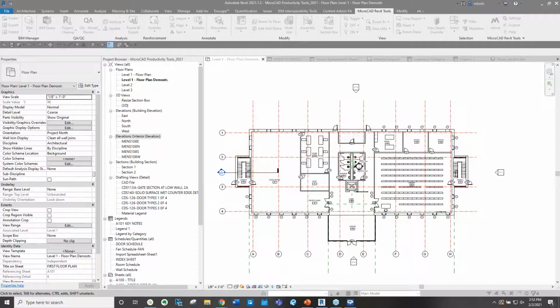So what the BIM query kind of does, it will pull the categories, and basically, if you're familiar with Excel, you have your different sheets at the bottom. So you're going to have your furniture on one sheet and your lighting fixtures on another. And of course, you're going to be able to pull those parameters. It just kind of depends where you're trying to go with that in the end. I don't think you're going to be able to like stack them right on top, like your furniture is section 1 and your lighting is section 2. But it cannot be overall within the same file, if that makes sense. It's just on different sheets.